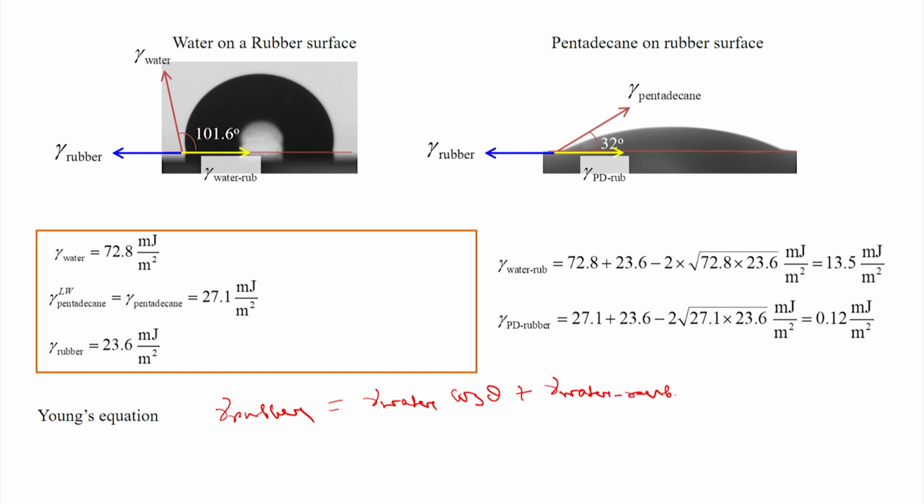See here we have this drop, and we can draw a tangent to this particular water drop, and this tangent makes this particular angle. Remember, you have dispensed a drop; it first spreads to some extent and then comes to some constant value. So a constant amount of spreading, after that it is not going to spread. This is the equilibrium, and since it was spreading during advancing, we call this particular angle theta here the advancing equilibrium contact angle. That is what we call it.